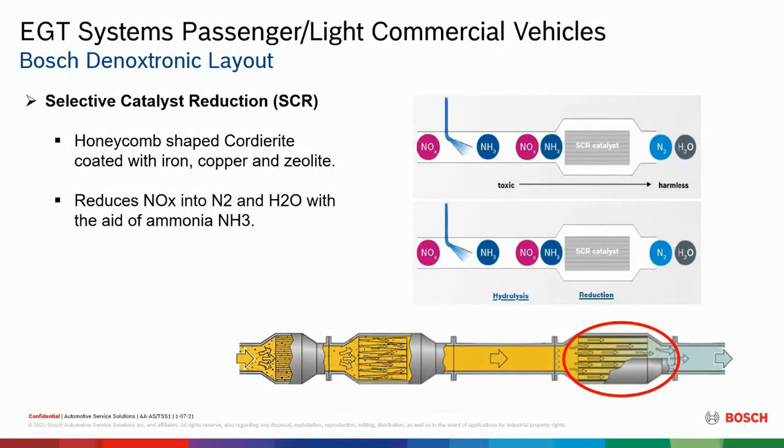All right. So what happens to the SCR when it goes bad? Again, same thing. It can get poisoned. It can get cracked. Very similar to all these devices. The same thing can affect all of these in order to damage them. So if you have an engine not running properly, all three of these can be affected. One might take the hit more if it's caught in time, and two of them might be able to be saved or whatnot. But the sooner the operator gets it in and it's diagnosed correctly, the better off we're going to be.